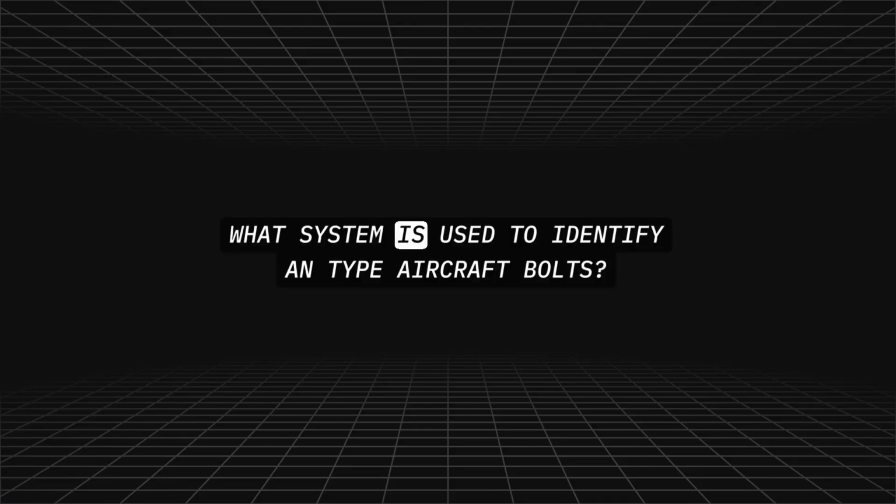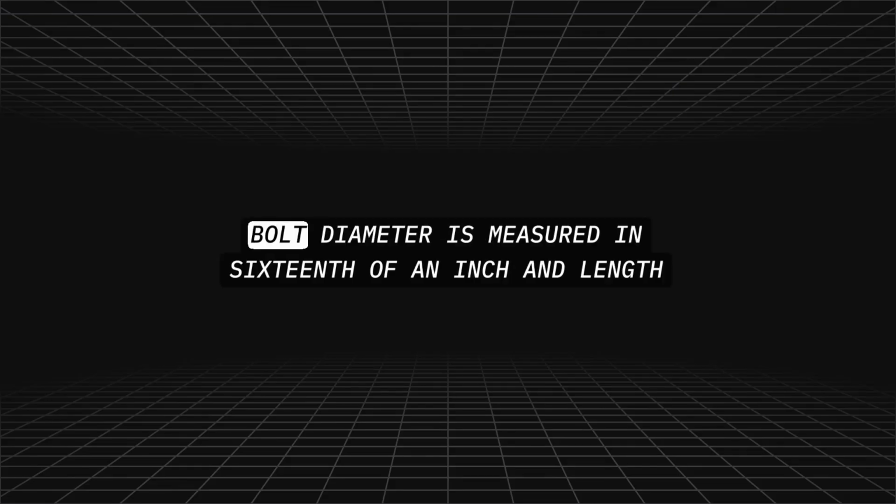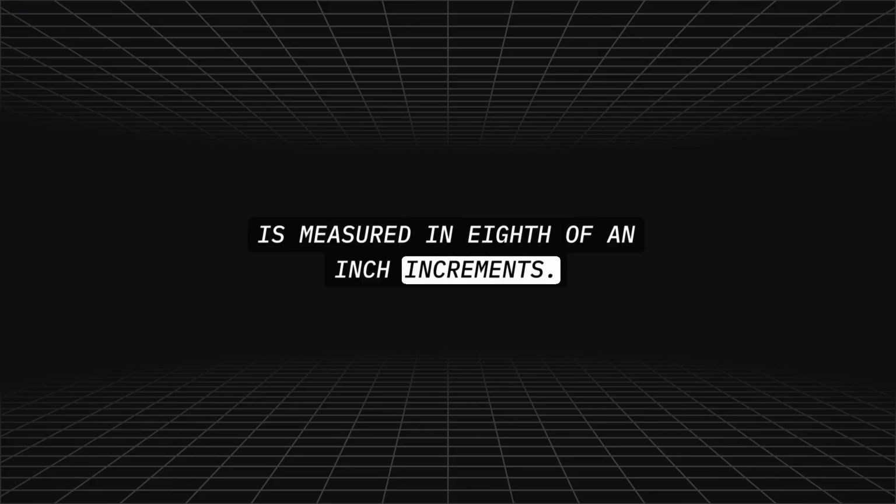What system is used to identify AN-type aircraft bolts? Aircraft bolts have code markings on the bolt heads for identification. Bolt diameter is measured in 1/16 of an inch, and length is measured in 1/8 of an inch increments.